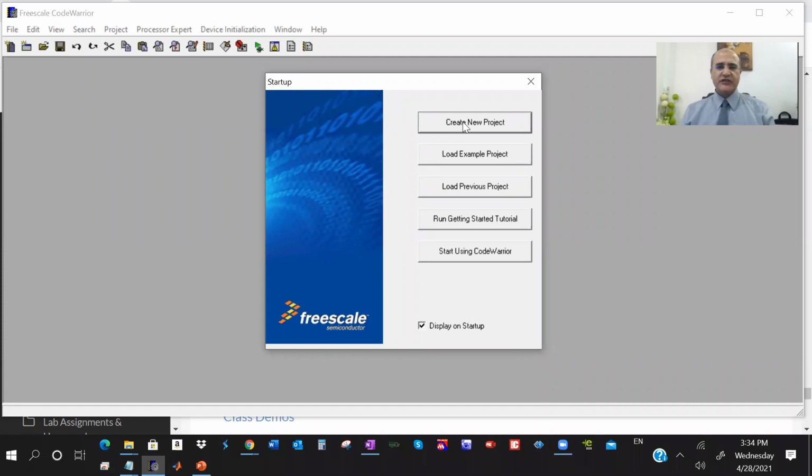So let's do this. Let's make a counter that counts from 0 to 9 forever and displays it on the 7-segment display already built in, connected to port H on our microcontroller HCS12. Of course, if we get an external one, we can wire it, but this is already wired for us.